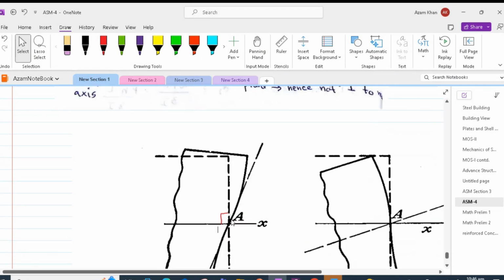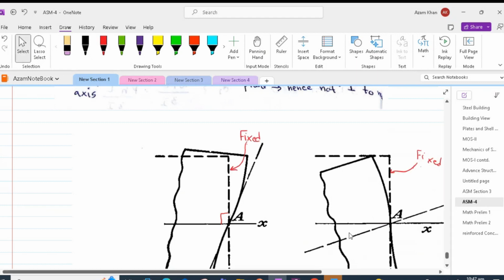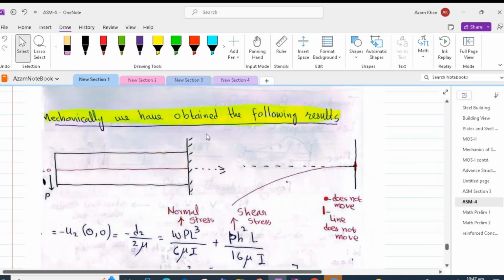We couldn't make all these fibers stay plane because that was too restrictive. So we had to relax some of the conditions and allow the fibers above and below the neutral axis at the root to have some deformation. Please note that we are considering this end as a fixed end. So this is at x1 equal to L in our case.